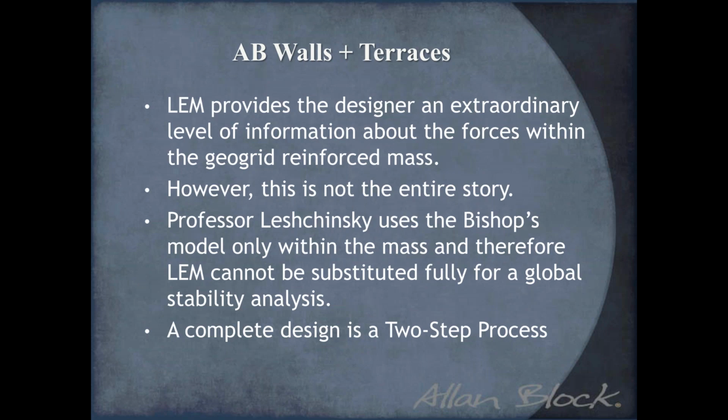Professor Lazinski has used the Bishop's model within the mass for LEM. And again, I want to emphasize, like I did earlier, that it doesn't replace global stability, because of what I mentioned before. All the exit points come out of the wall. None of them go under the wall. So global stability has no limitations, and the LEM is limited to the design envelope of the wall structure itself, the infill and the retained soils, never the foundation soils below the wall.